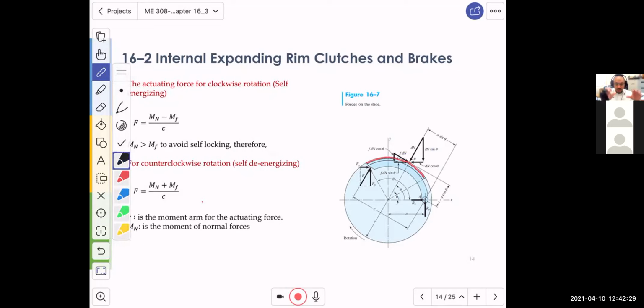However, the brake, but this is actually, I'm going to call the red one the pad, but the shoe itself is this. Look at it. It's going all the way to here. You see that? It's taking almost a quarter of the circle. But the shoe is located only on a partial portion of it. Now, I told you that we are going to pin the shoe. That's why we have two reactions in there.